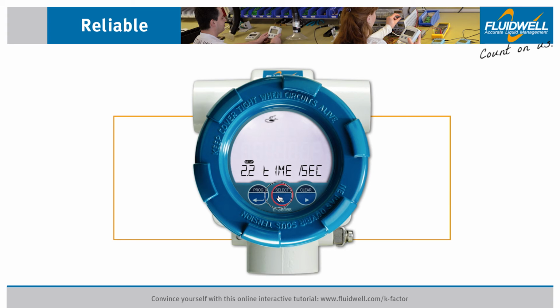Go to Menu 2.3 Decimals. Press Prog to change this setting. We select the 0.1 value. Press Prog to store this setting. The decimals for the displayed flow rate are now set to 1 decimal. Use Select to go to Menu 2.4 K-factor. Press Prog to set the K-factor.